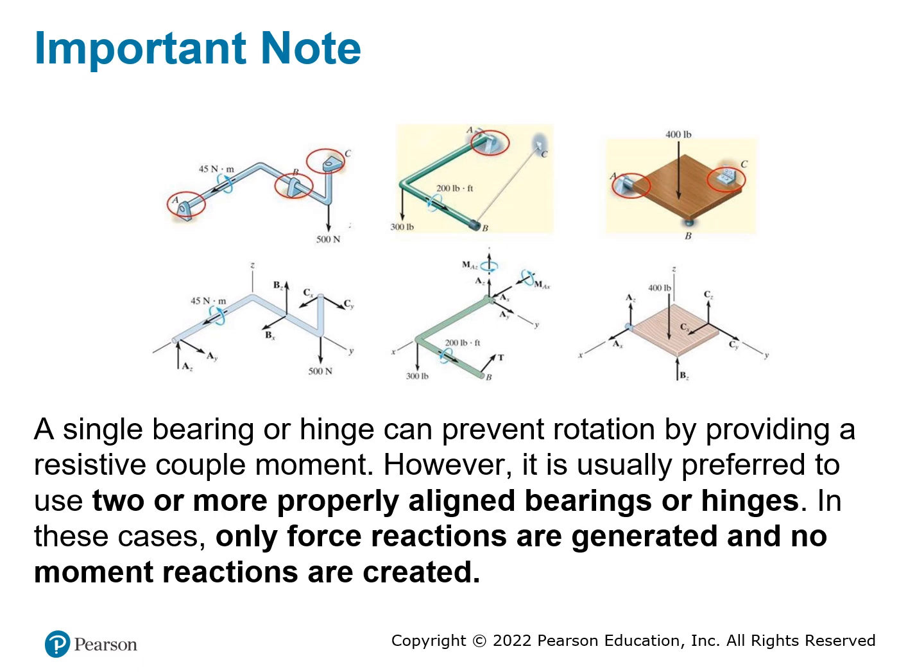But if you put multiple hinges or multiple bearings, you don't need to put those reaction moments anymore. That is because the design of multiple bearings would not allow it to rotate in any way. So you only need to put the reaction forces, and you don't say, oh, this is not going to rotate in this direction, so my Mz will be none.